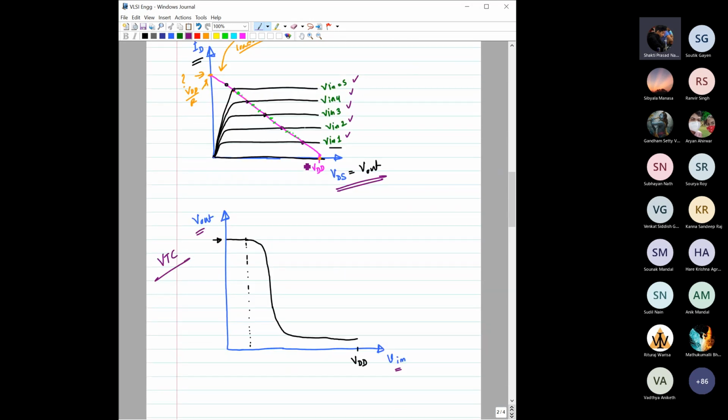So from that, you know that, right? Until and unless we are reaching this VTHN, the threshold voltage of this NMOS, the current would be zero, and the output voltage would be constant at, please tell me, VDD. VDD only. Okay, so till VTN.